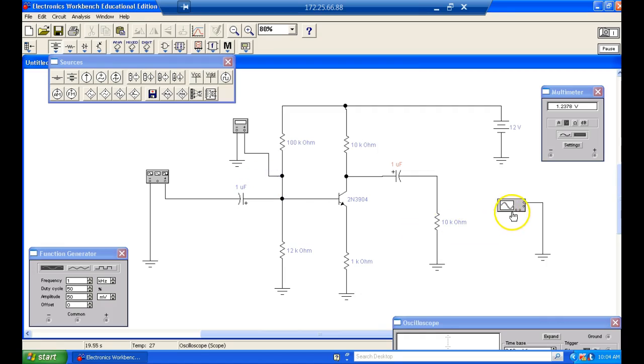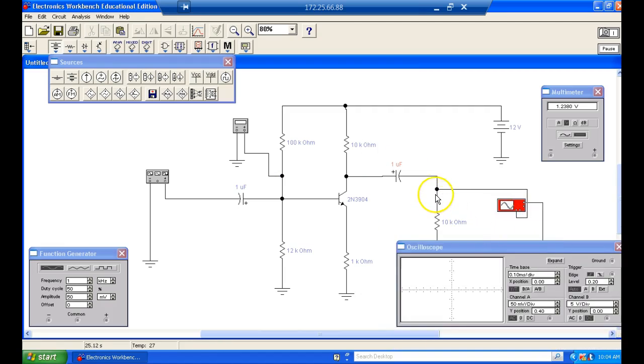So the only thing I'll be able to do is find this with an oscilloscope. We measure right here. It measures 0. We measure right here, the gain is going to be a lot higher than what it's supposed to be, because now it's a gain of 10 instead of a gain of 5, because we lost our load, right?